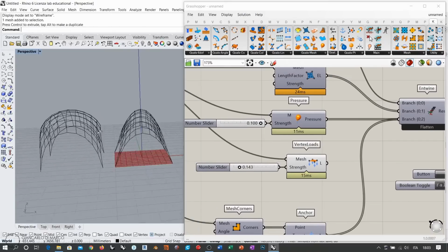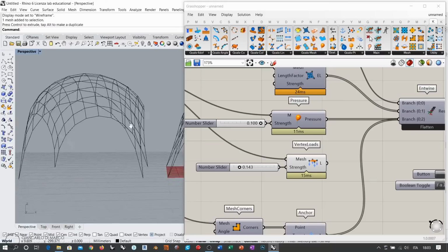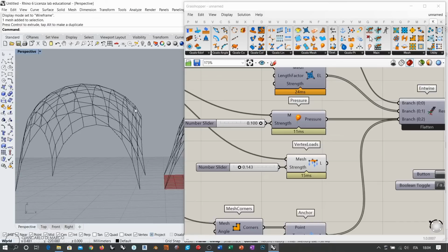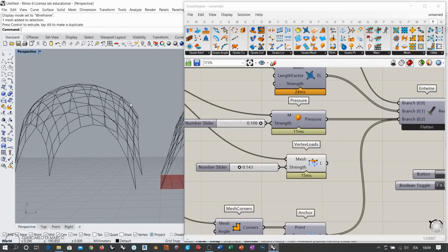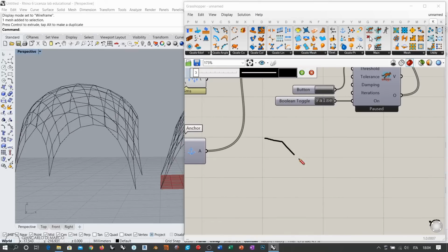While pressure acts on the polygon, and when the polygon changes its orientation, for example, like this, for example, I have many polygons here. If I have this inclination, pressure is acting on the face in this direction. While vertical load, no matter the deformation, always acts vertically, right? So in this case, pressure will be pushing like this.